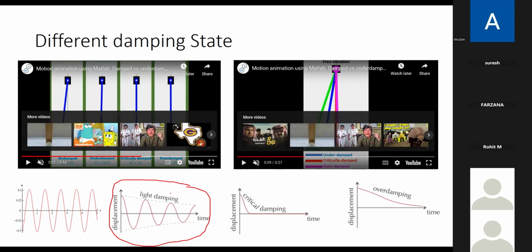So to quantify mathematically, they compare this underdamped with critical damping. So these two we will be comparing. Critical damping means 100%: within one oscillation, my building will come to one position. Underdamped means, compared to critical damping, how much oscillation it takes to come to its original state. By comparing, we will say what is the damping ratio.